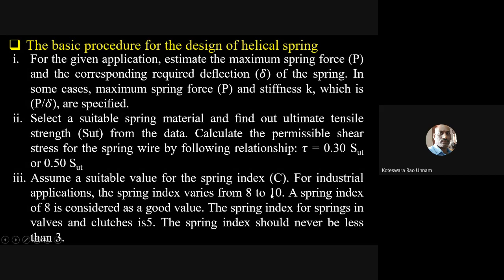So you need to pick the spring index between these two values, 8 to 10. Spring index 8 is considered a good value. Generally, if the problem doesn't specify anything, you take the spring index as 8.